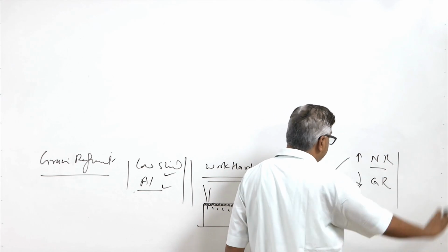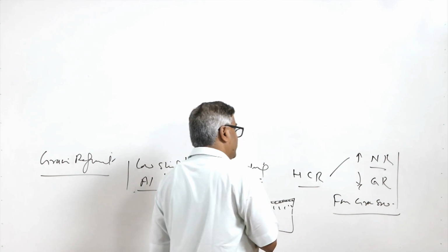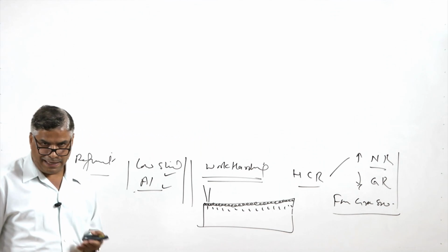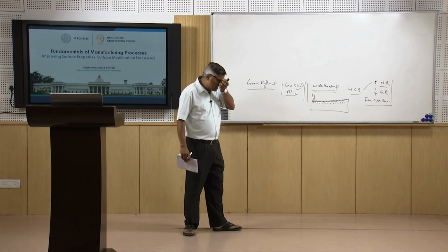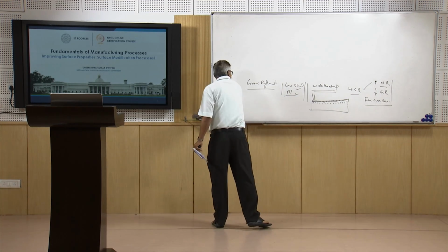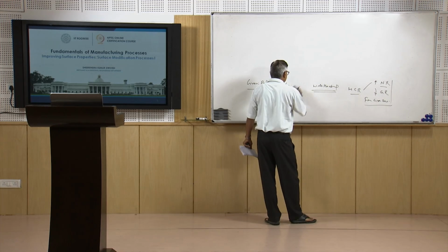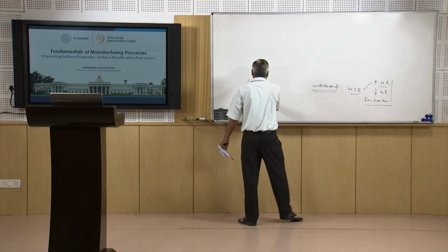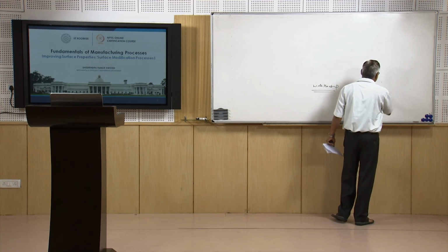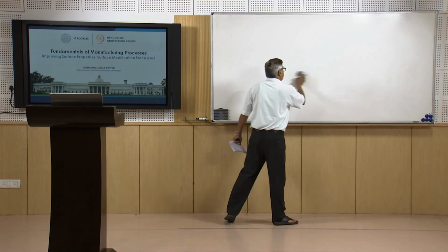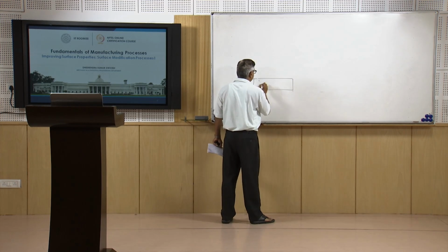So, whenever this combination is present, we find very fine grain size in the metal, and that is why TIG melting of cast aluminum alloys and laser melting of steels lead to a very refined grain structure. Work hardening methods are applied for those systems which do not respond very effectively to heat treatment or thermal methods. In those cases, near surface layers are deformed intentionally plastically, so that work hardening can be facilitated. We know that if the material is having few